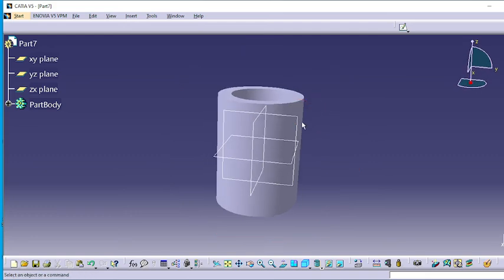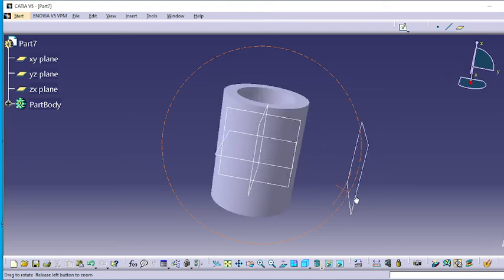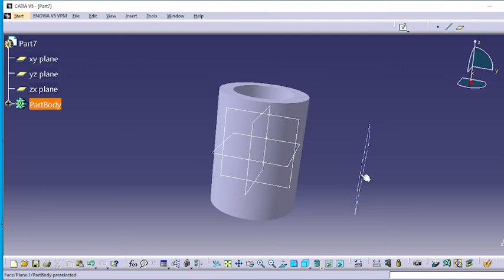Okay, so this plane is there. This plane is the side plane. For this side plane I need one more plane, for example. The same side plane, I require one more plane. So this option is there. Select this plane. Now you are using the select plane option. So an offset value is there, 100 distance. 100 distance means I am taking the same plane with 100 distance. You know the offset command, right? Same way, you are taking the same plane with offset 100 distance. Select this plane. Now you can click on the sketch option.